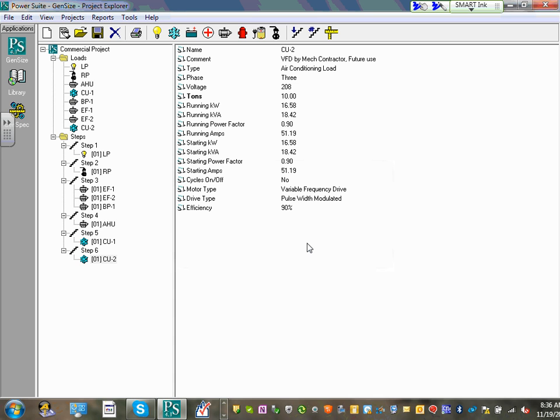So the whole idea, Adam, when you put loads on steps, the bigger loads, leave them until the end, especially not the most important. I mean, chiller, okay, people can live for 10, 20 minutes without chilled air, but light, you need them. Receptacle, they need to be up and running, right? So your light, typically emergency light, the first step, then receptacles, then data if you have data.